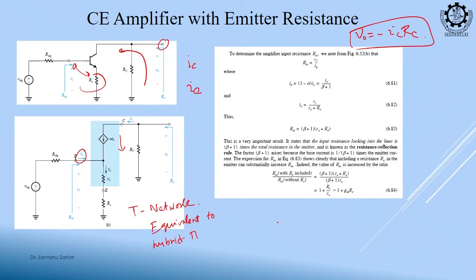Okay. So, it is drawn like this. I am having IC, I am having IB, and total KCL is IE, clear. So, I will write this IC in terms of alpha, alpha IE. So, IC is equal to alpha IE. And what is the looking-in resistance in the emitter terminal? That is small RE, right.